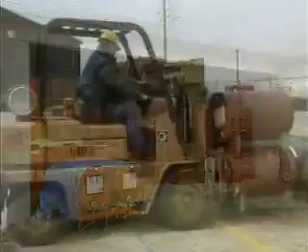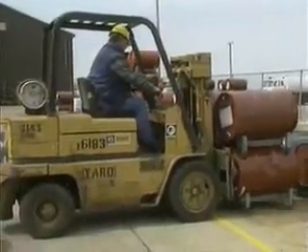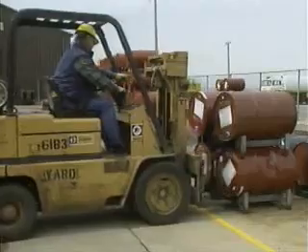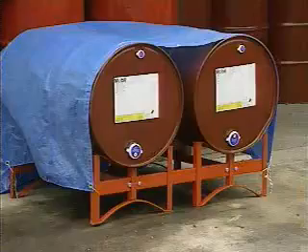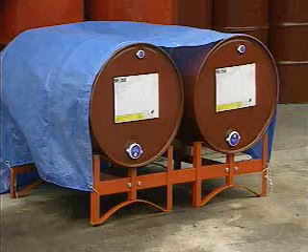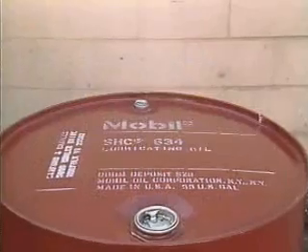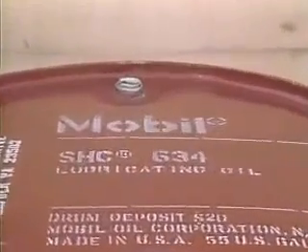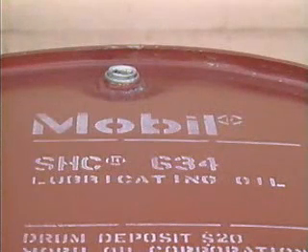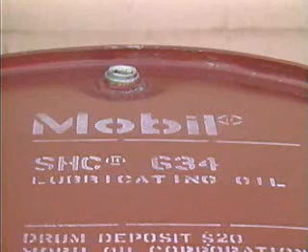Generally, metal drums of lubricant should be stored either upright on pallets or horizontally on racks that keep the containers off of the ground. You see, storing a metal drum on a rack keeps the metal of the drum from contacting the ground or standing water. This helps prevent the destructive chemical reaction of corrosion from occurring. In addition, storing a drum on its side prevents water from collecting on the top of the drum. Water that's allowed to collect here can eventually penetrate the seal around the drum's opening and contaminate the lubricant that's inside the container.